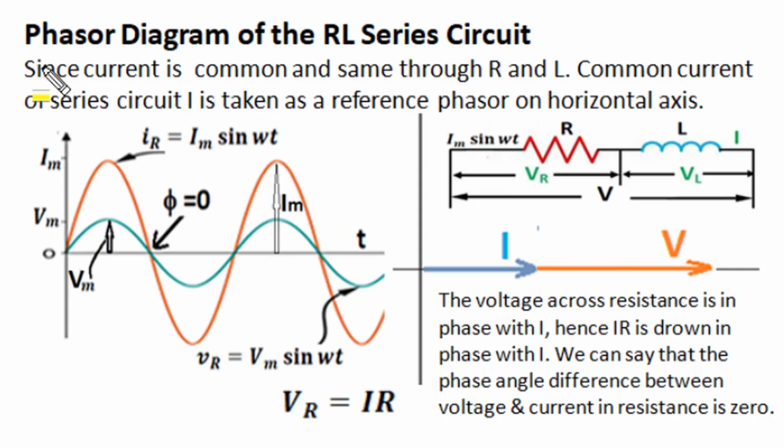To find the complete phasor diagram of the RL series circuit, we'll first find the relation between circuit current and voltage of resistance, then we'll find the relation between circuit current and inductor voltage, and then the sum of resistance and inductor voltage will give us the total voltage, and by that we'll get the magnitude relation between RMS current, RMS voltage and the phase difference angle between supply voltage across the RL series circuit and current flowing through it.